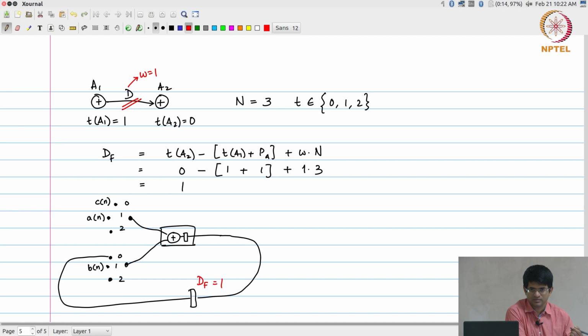Of course, you need to keep one thing in mind. I arbitrarily did one pipelining step over here, that is to say I inserted one iteration delay between a1 and a2. But keep in mind that if I am actually doing pipelining, I need to make sure that since my original graph looked like this, in principle, even though I am not marking them, these are also nodes as far as this system is concerned, which means that a proper pipelining will have to be like this. If I insert a delay element over here, I also need to insert one delay here, so that the c gets delayed appropriately by one clock cycle before it is being applied to the input.